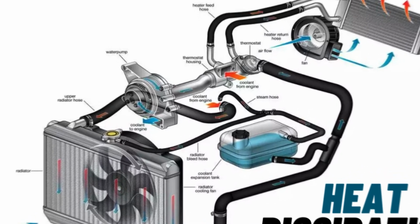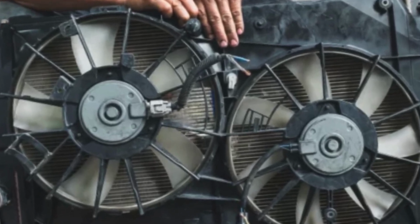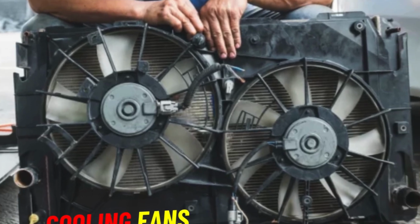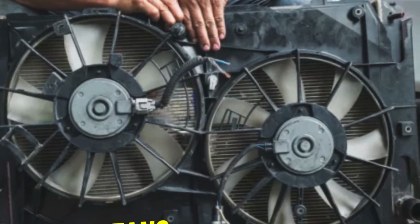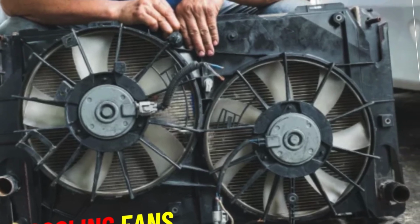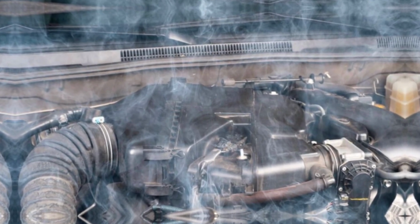Number 2. Cooling fans. When the vehicle is stationary or moving slowly, electric or mechanical cooling fans provide additional airflow over the radiator. These fans are controlled by the engine's temperature sensors and activate when needed to ensure continuous air movement across the radiator fins. This consistent airflow is vital for maintaining cooling efficiency, especially during idle or low-speed conditions, preventing the engine from overheating.